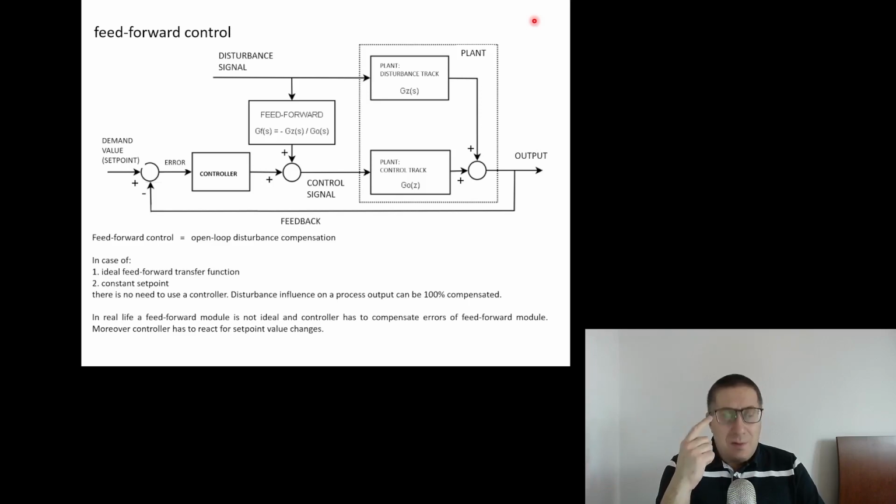Okay, so in such a case, my PID controller in my head will send a control signal to my hand that will change the valve position in this radiator over here. So if this is a radiator supplied by hot water, of course there is a valve. If I open this valve, the more hot water will enter the radiator, the more heat will be generated and transferred to my room.